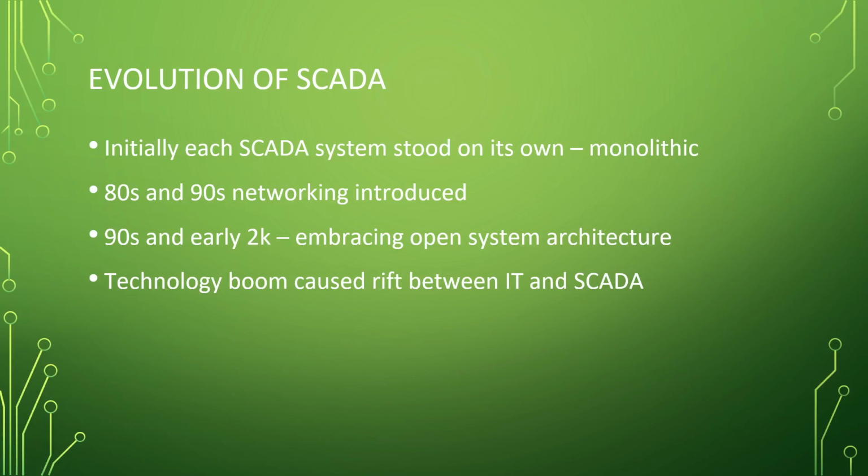HMIs are absolutely wonderful. PLCs, the bomb. HMIs, close second. Because HMIs allow you to show the operator lots of information. If the PLC detects an error, you could just flash a light to say there's a problem. The HMI can say error 32, and you'd ask, what's error 32? And you're like, oh, sensor malfunction. Okay, I now know. Before, without an HMI, you had to have an error light for every different number. So if you had 100 different error codes, you'd have to have 100 different outputs for each light. That's a whole other PLC's job, basically, to have that many outputs.